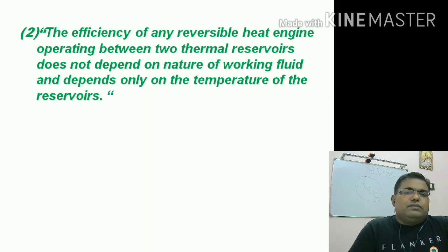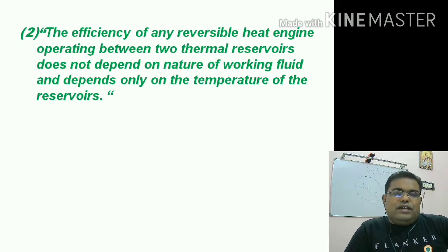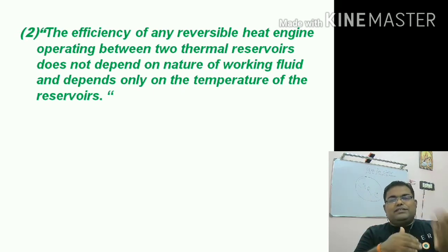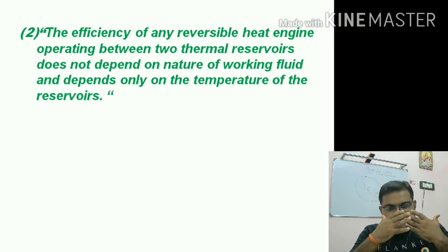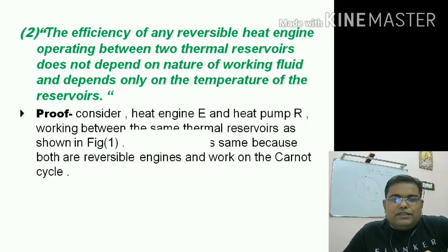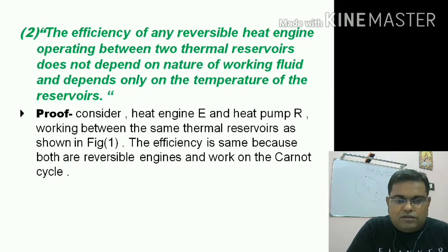Second corollary of Carnot: the efficiency of any reversible heat engine operating between two thermal reservoirs does not depend on the nature of the working fluid, and it depends only on the initial and final state of the system, or you can say it depends only on the temperature of the reservoirs. So keep in mind, reversible heat engine performance does not depend on the properties of the working fluid. It depends only on the initial and final temperature of the cycle, or you can say only on the temperature of the reservoirs. So again, I will prove this by the simple analogy which we followed earlier.